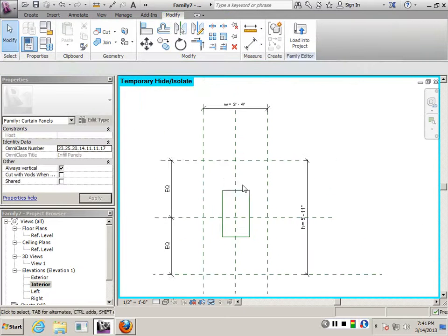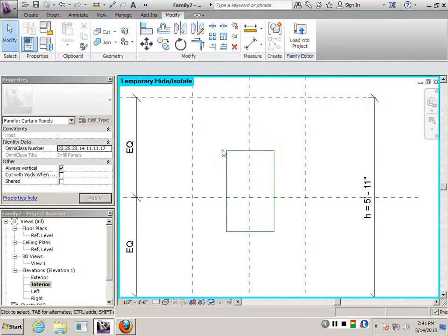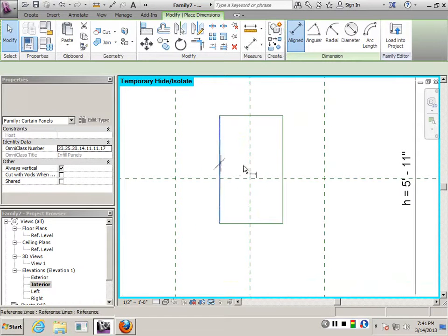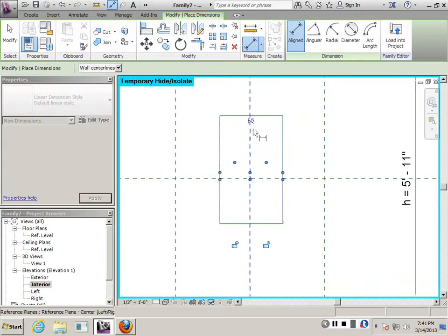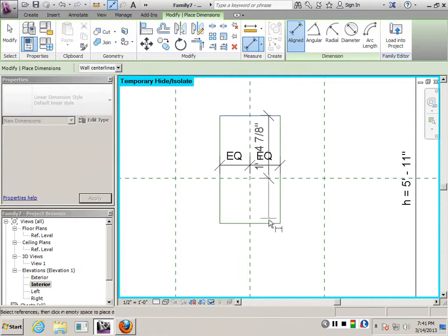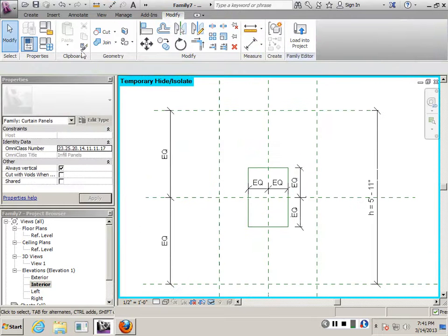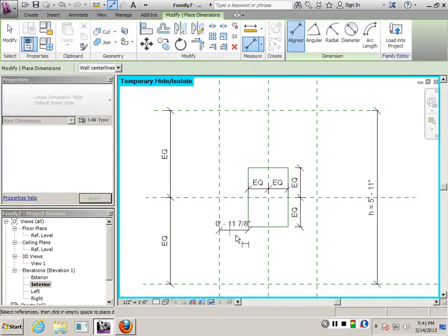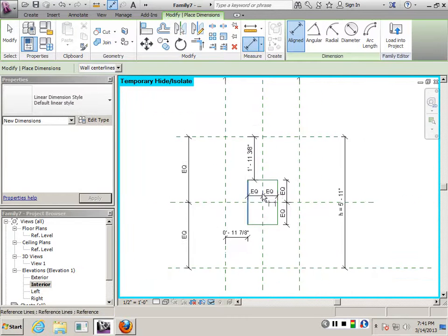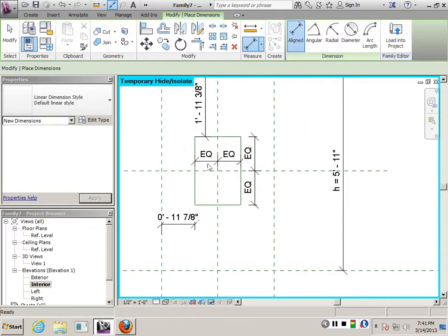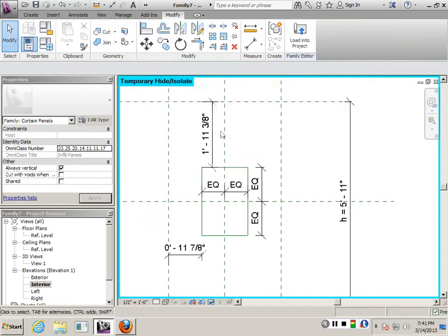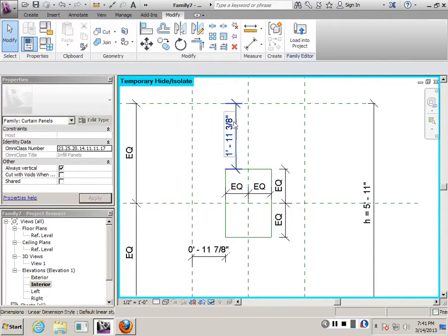But what I want to specify is these offsets. So maybe we could first use the annotation tool and make it symmetric on both sides like this. And then I want to create another annotation that specifies the offset from both sides. So one from the top and one from the left. I don't have to create one at the top and the bottom, because if you just specify this dimension, since these are equal, it will create the rectangle. Okay?